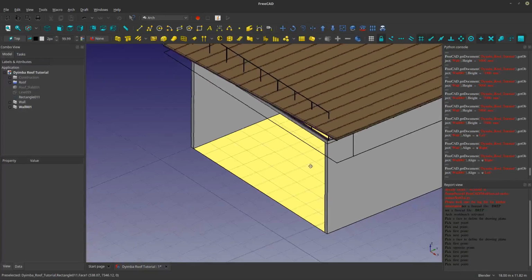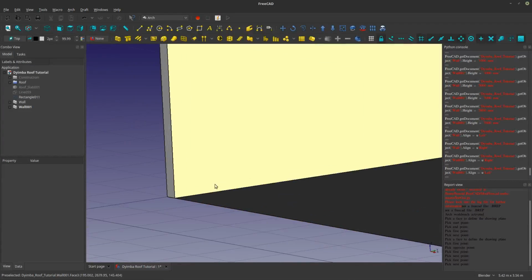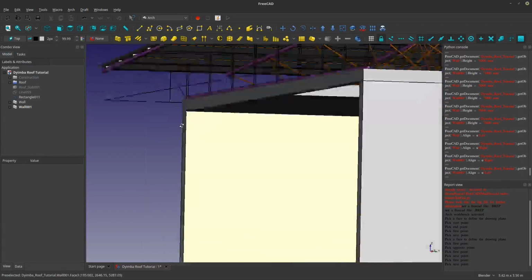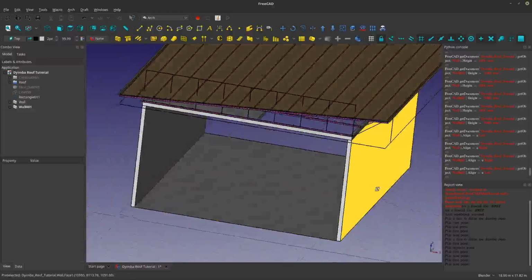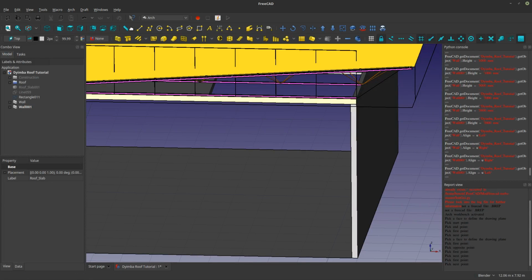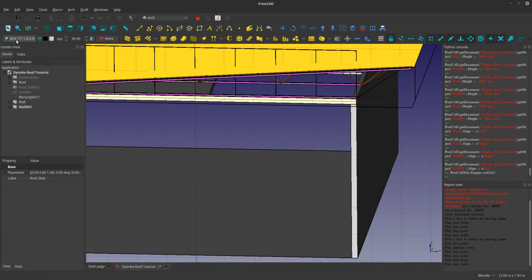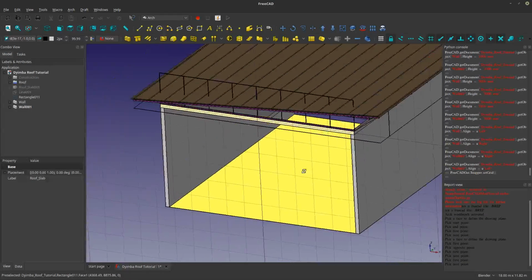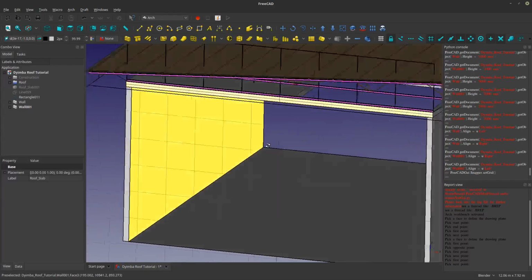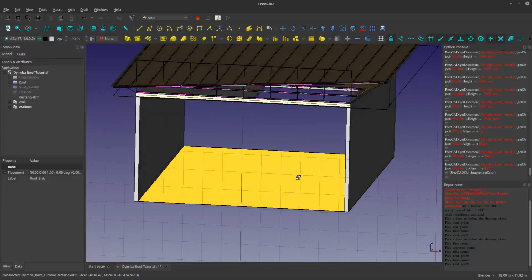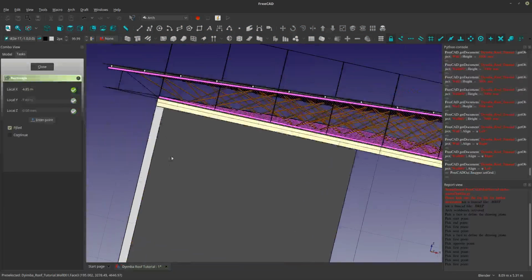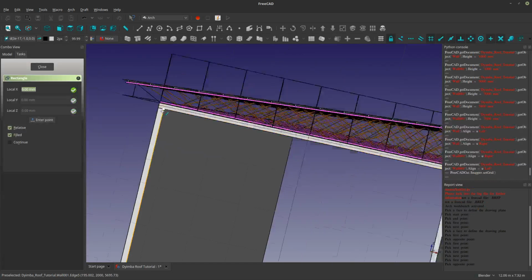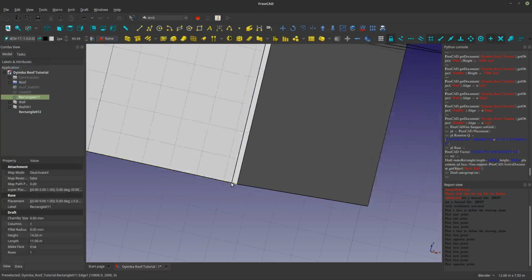So let's see. I want a curtain wall that's gonna be inside this space. So now, what do I do? I select this face and put the working plane on there. And so this is where I can begin testing now. So I can say, okay, I want a curtain wall. The initial immediate reaction that's going to come to mind would be to do something like this.